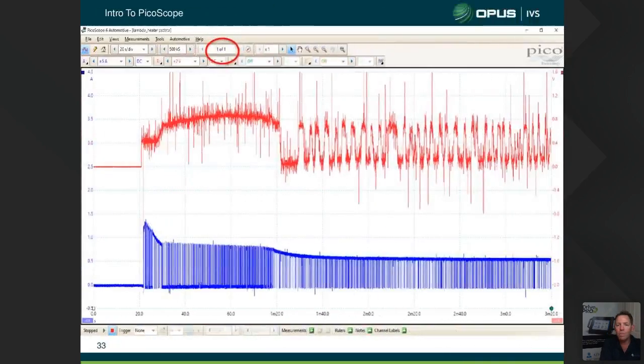Okay, our next slide. What we're looking at here is our waveform buffer. Now, waveform buffer is really, really good for reviewing waveforms that we've just captured. So this will capture 32 screens. So this is one screen here, and as the pattern rolls in the next screen, it'll basically record to its memory 32 of those screens.